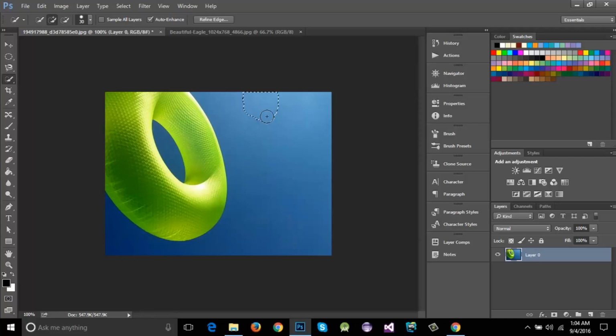You can see that it keeps on detecting the color range, or the contrast or the brightness inside an image, and adds my new selection area into the previous selection area. I have selected this area. Now I will click right here. You can see that it has detected the bluish color from the above selected area. As I clicked the same color just at the bottom of this image, it has combined the selections and selected all the areas that come within that color range.